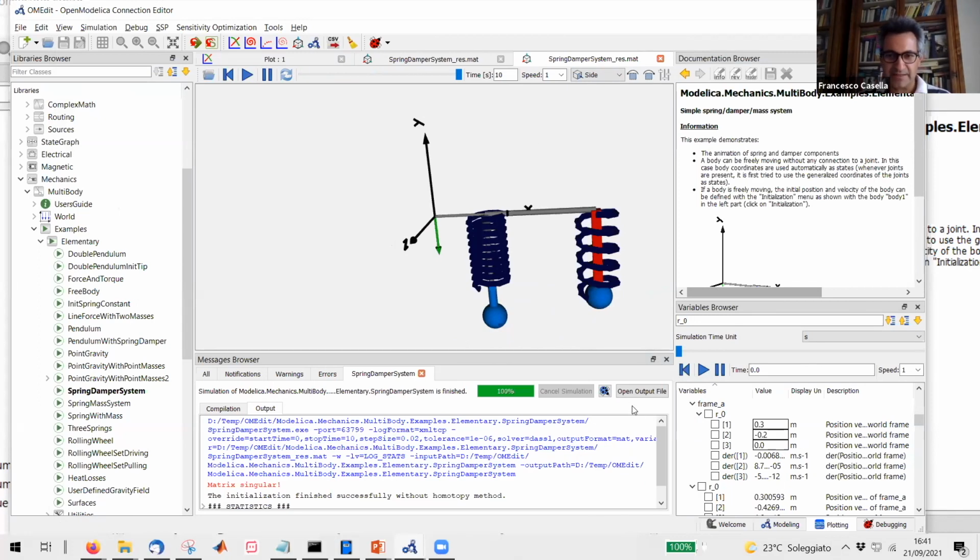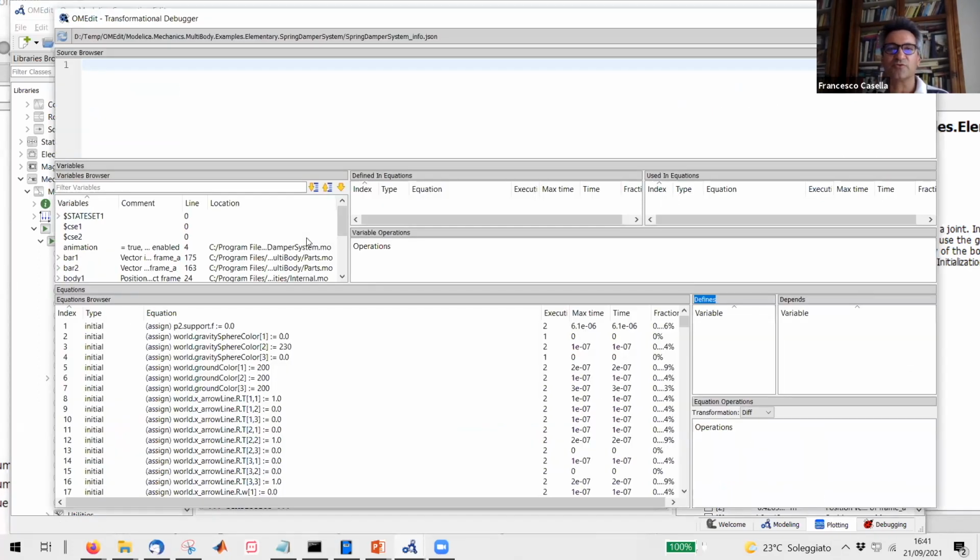What is not so standard, as I was mentioning, is the debugger. Let me show that to you briefly. As you may know, there is a lot going on in Modelica tools. You start from an object-oriented composite model, which is equivalent to a bunch of differential algebraic equations. And then these are subject to a lot of symbolic processing. They are solved symbolically, sorted, lots of stuff is going on until they get to the form which is very close to the solver, and that's the stuff that actually runs when you run the simulation.